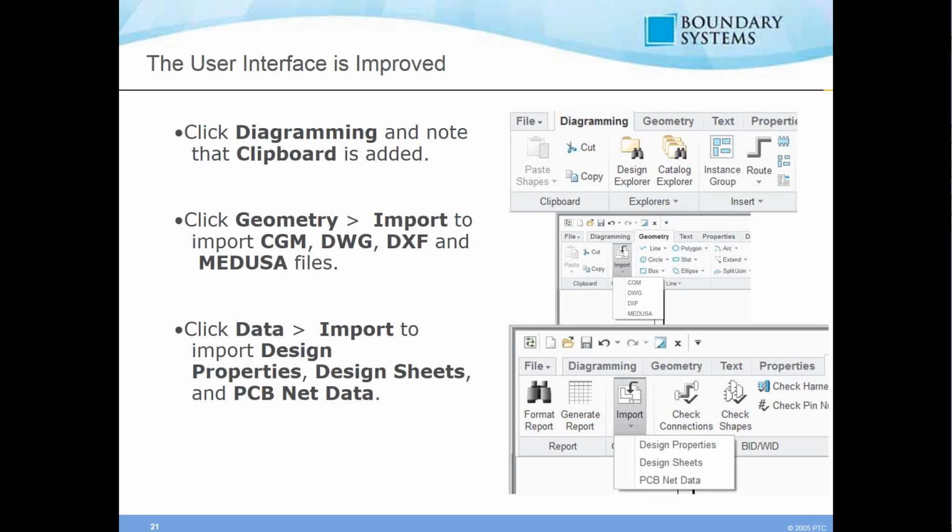Okay, also, if you take a look at the geometry tab, the next one down, you can go to import, so you can import geometry. And it gives you a list of the 4 basic types of geometry you can import. So if you have things like AutoCAD files, something of that nature you want to import for geometry for your blocks, then you can easily do that right here in the import group in the geometry tab.